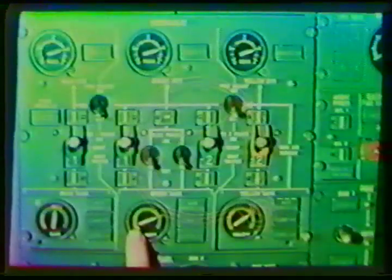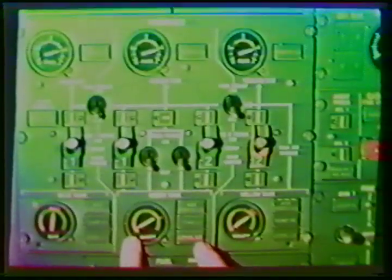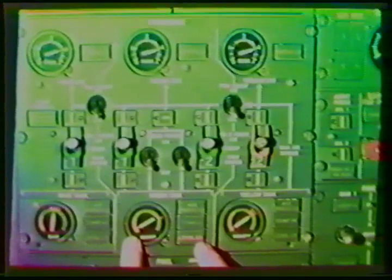When the indicator needle drops to this red point, the level low warning is triggered and the amber light illuminates. The capital letter T, which appears in the lower left corner of the warning light, stands for test. The T signifies that the warning circuit may be tested by pressing the light caption. The capital D in the lower right corner means that the light may be dimmed.